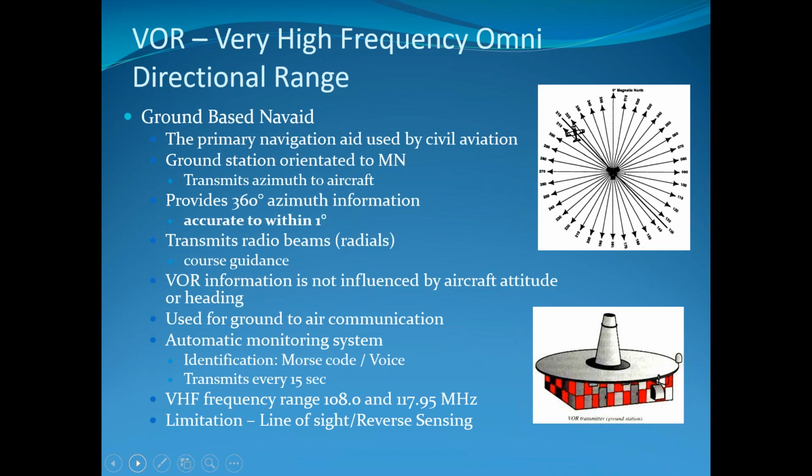So if a pilot is talking to air traffic control and they give him the wind, same deal, that's going to be magnetic because he's hearing it. But a dispatcher typically reads it. So what a dispatcher sees is normally going to be true. What the pilots see is normally going to be magnetic. So why it's just not automatically converted for us, I don't know. Just one of those things, kind of like the whole Zulu time. There's several of those little concepts, but it is what it is.